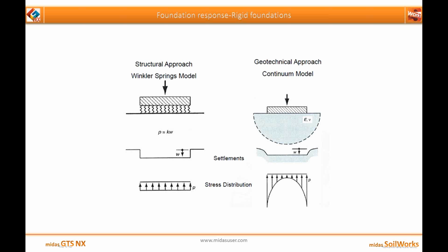That is, we have a very non-uniform pressure distribution with very high stiffness at the ends. And also in the settlement you can see that there is a curving at the ends. That is also not considered when one goes for the structural approach, and this is how the foundation response differs whenever you are considering the rigid foundation.